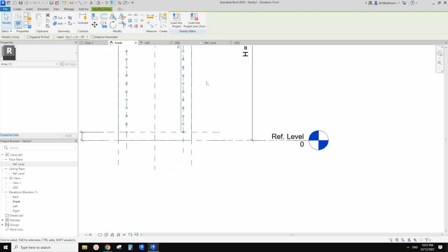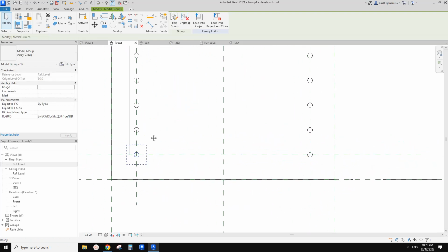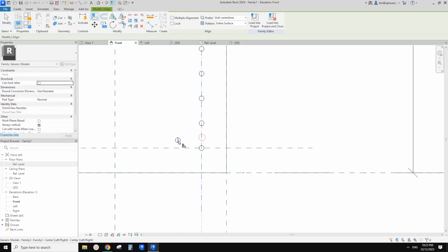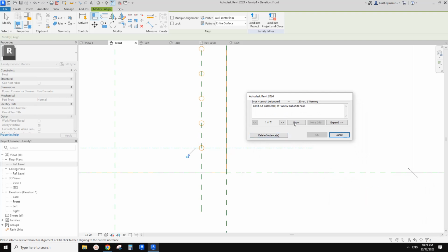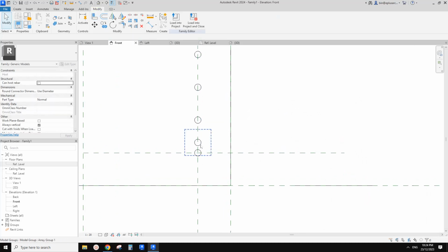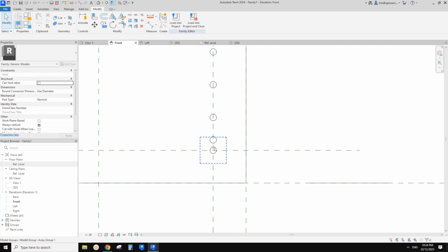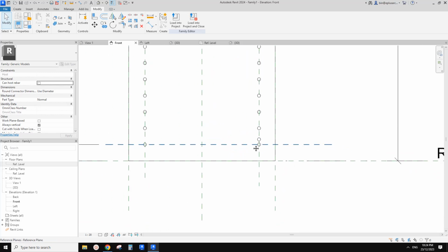So now we have another array. And then the last one is slightly different, so I'll show you why. AR here to here, and try to align, no problem. And this one, okay, we have some issue here. You can see Revit won't let us place another one here, because when we place this one here, we need a base, but there's already a void there, which means there's no solid part there to be cut by another void. So it won't work. That's fine.